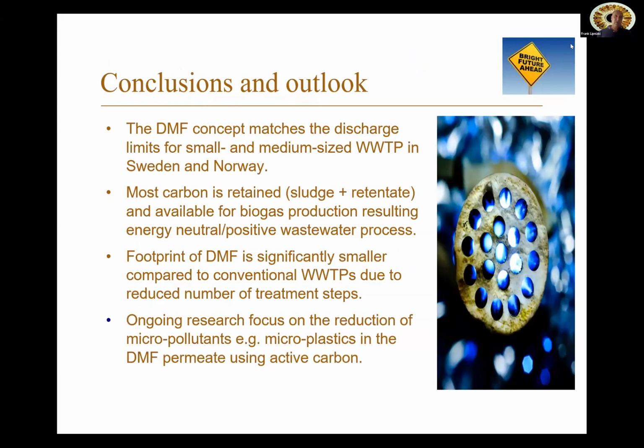With this, I come to my conclusion and outlook. What we see is that the direct membrane filtration concept matches the discharge limits for small and medium-sized wastewater treatment plants in Scandinavia. That means especially Sweden and Norway, where we did the trials. Most carbon is retained as sludge and retentate, and you can then use it for biogas production. That means the whole process, if it's designed properly, is an energy neutral or positive energy wastewater treatment process. That's something I think is quite excellent about this process.